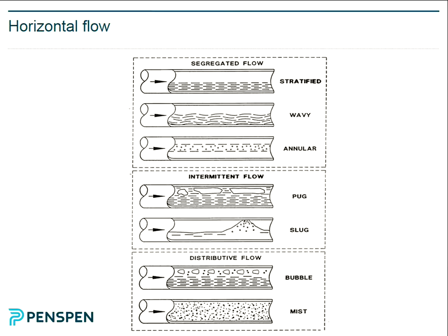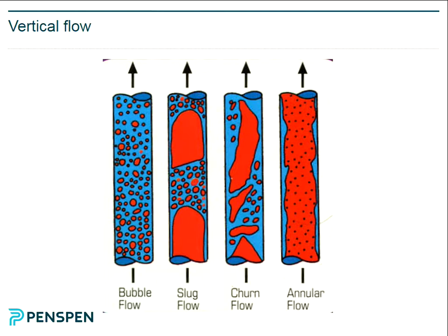So a special example. We've got horizontal flow, vertical flow, but actually when you do multi-phase flow analysis, you'll find that some correlations will actually have angle in them. Some correlations, hold up and pressure drop correlations, are for either horizontal or vertical. But some actually have angle built into them. So with some correlations you have to have a switch. You can say anything more than 45 degrees, I use vertical. Anything less than 45 degrees, I assume it's horizontal. Some correlations actually have the angle in them. So that's again part of the analysis.